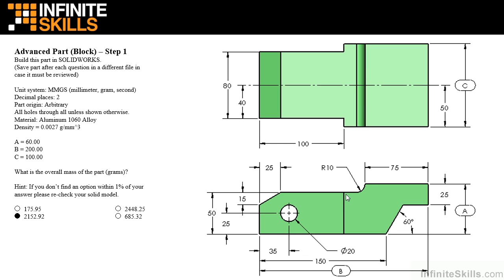And then create another sketch of this profile of the right half, and extrude that profile about a mid-plane, a dimension of 100. The most efficient option is to create your sketch to look like this front view, to show all of these perimeter lines along with this vertical line and the circle. And then we can use the selected contours option in the extrude feature and specify the exact profile we want to extrude and the distance we want to extrude it. So that's the approach I am going to take. Let's go to the SolidWorks screen and build this part.